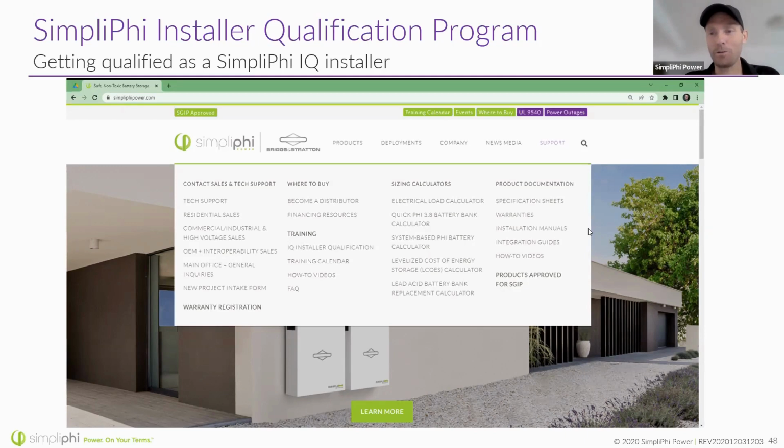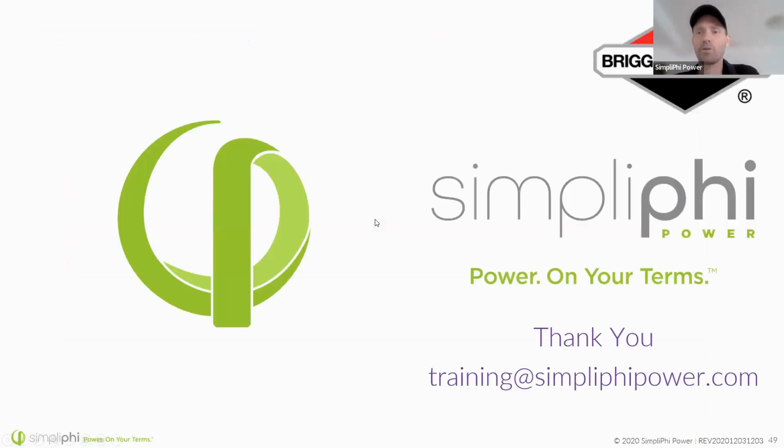Tom says, thank you. Michael says, you're welcome. Michael asks, do you have discharge graph curves for 24 volt you can share? I think so, Michael. Can you send me an email at training at Simplify Power, and I will get you the discharge characteristic for a 24 volt. The answer is it's exactly cut in half. So if you look at the 48 volt one I shared, cut it in half, that would be a 24 volt.